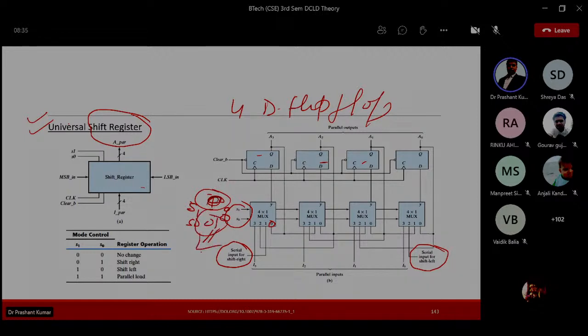So it selects input 1, and similarly the others. So when S1 and S0 are 0, the present state of this register is applied to the D flip-flop, and this condition forms the path of output, and the next clock will actually trigger it, where the clock is a common clock here. Fine.